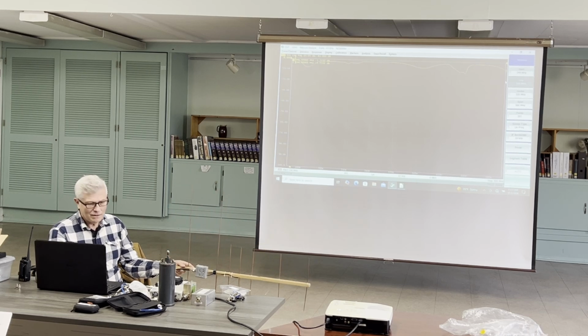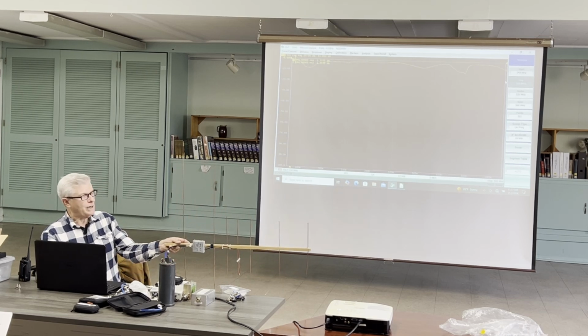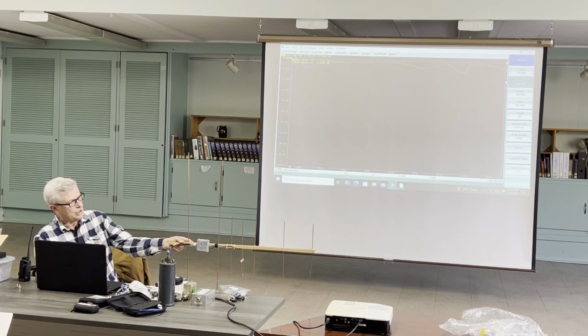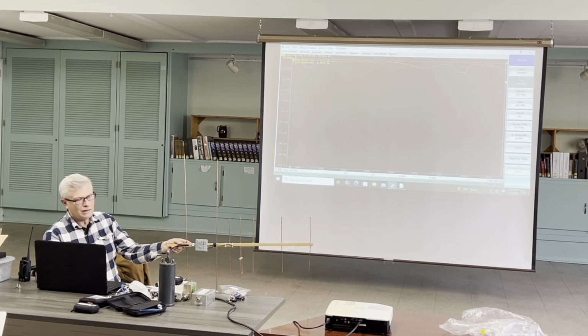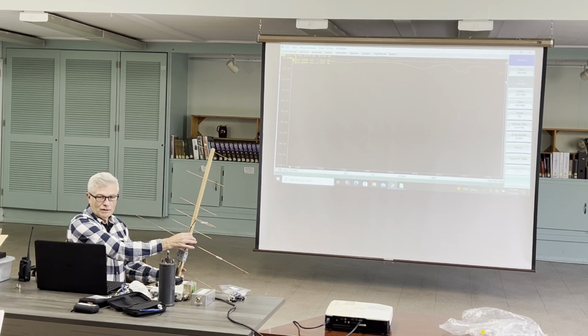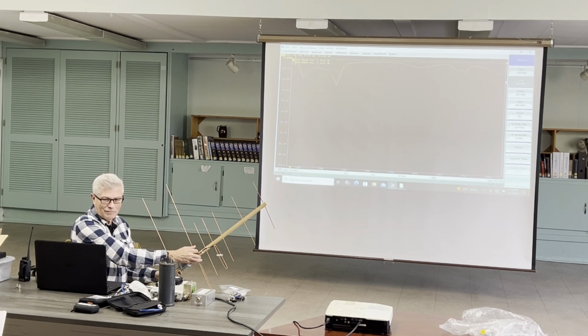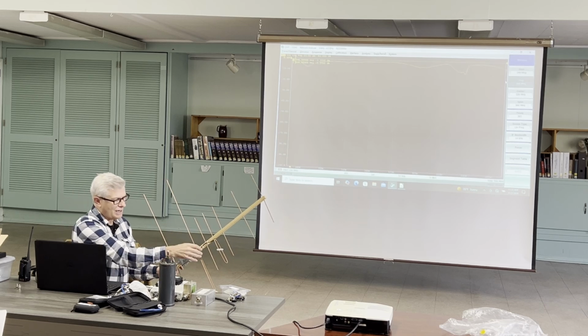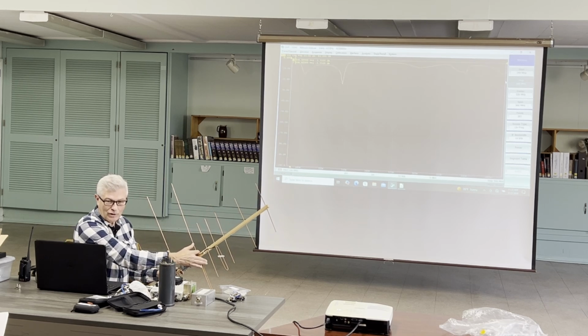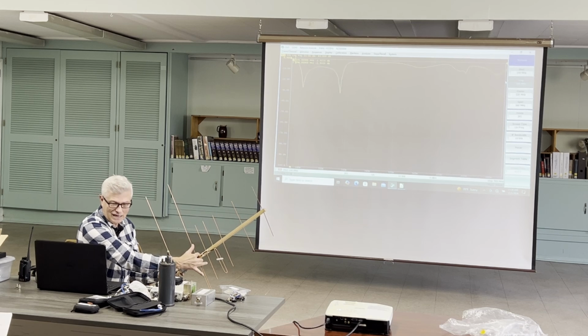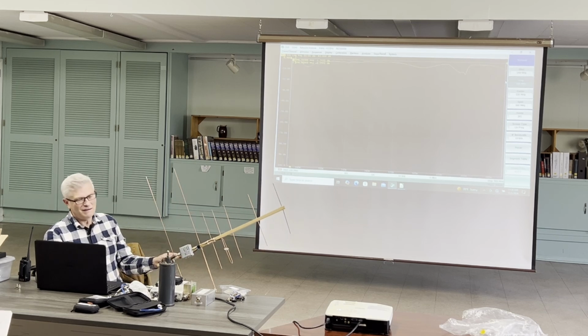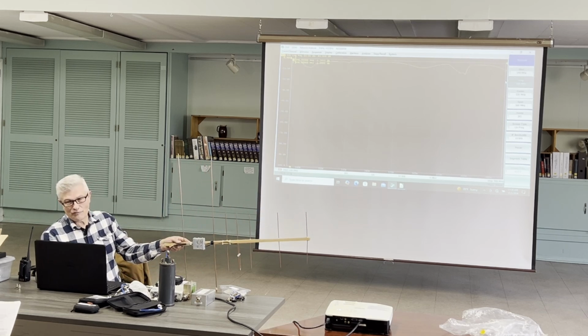But of course, again, you really want to do this in free space. I don't want to be influencing it too much because it's a directional antenna. If I point it toward me, oh, look what I'm doing. I'm putting my hand on here. Okay, I'm tuning it with my hand. So look at that. I'm knocking the antenna off of resonance by doing that. Well, or into resonance, as the case may be. But I'd say it's, for a first shot at this, Lou.